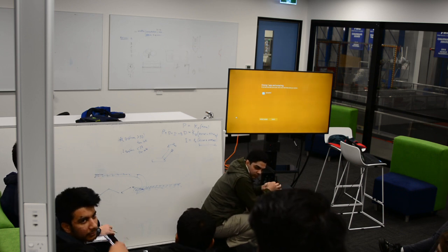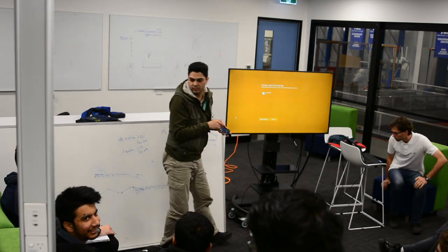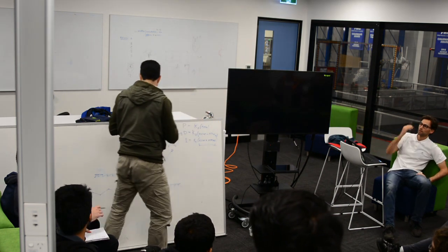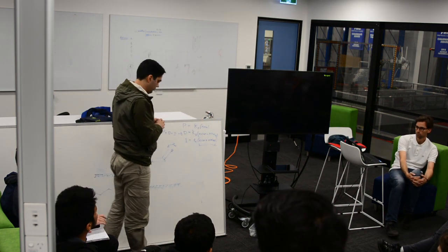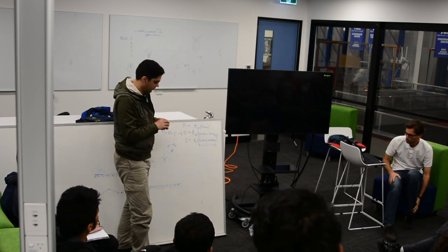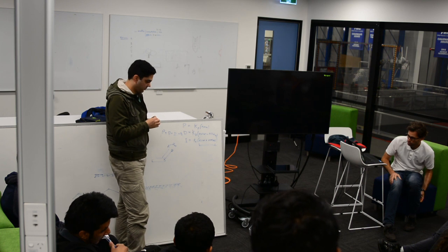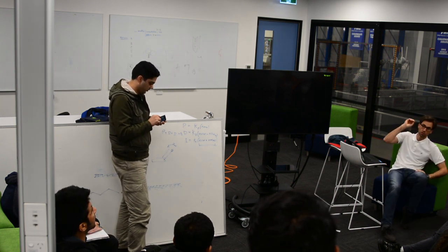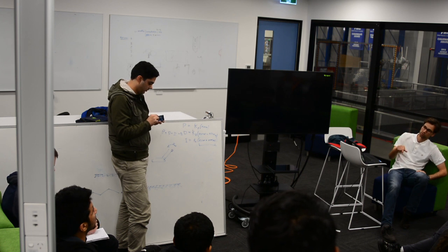You probably talked about this already, but when you're doing the target position and the number of counts, how does the code know where the current number of counts is? So that's the job of the interrupt service routine in a sense, right? So the interrupt service routine, when we initialize it, we set the counts to 0.